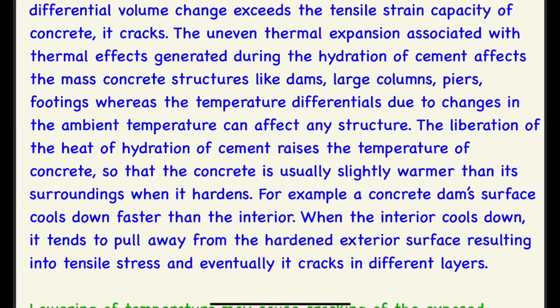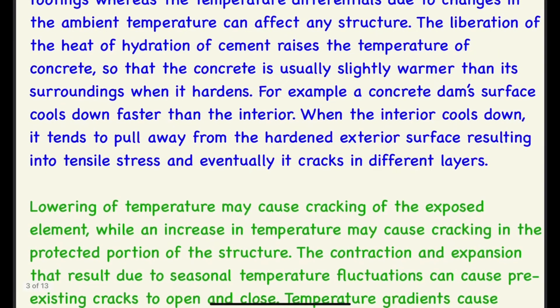See, if there is a wall and here the temperature is different and here the temperature is different, so the interior is cold, outside it is warmer, then it will produce tensile stresses, and those tensile stresses will lead to cracks in different layers. आपने देखा होगा कभी भी कोई वॉल भी आप करते हो तो आपको क्रैक दिखाई देंगे, अगर आप कभी देखो तो. Wall means concrete structure, sorry, not wall, concrete structures.